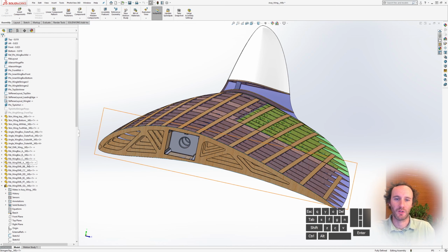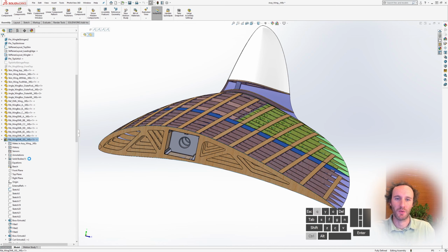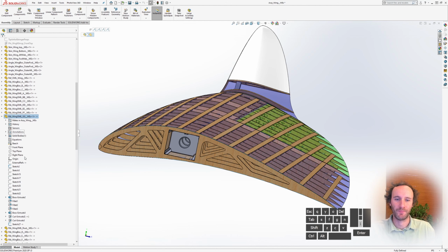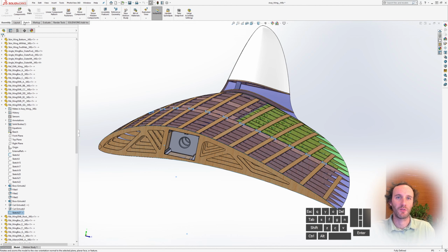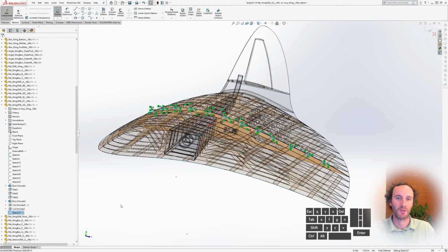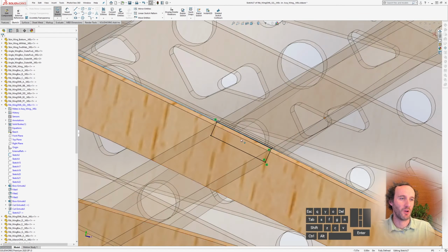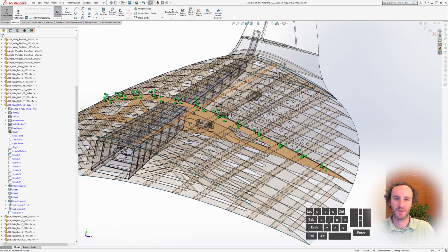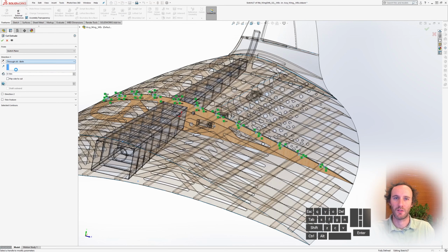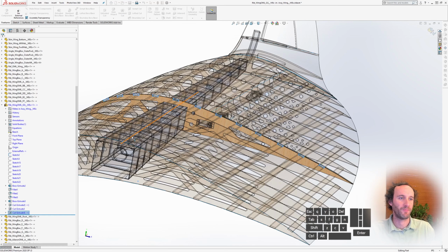Now if we go into this rib and Control Q that rib, go into its sketch. Now these top intersects of the stringers don't intersect the extrude sketch of the ribs. So we can use this for an extrude cut through all both.